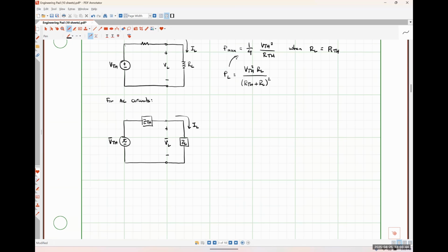Well, we know that the average power absorbed by my load impedance ZL should be, in the most generic form possible, 1/2 times the magnitude of VL times the magnitude of IL cosine the angle of theta VL minus theta IL, where this is literally just 1/2 VM IM cosine theta V minus theta I, like we just came up with 20 minutes ago for our generic system, okay?